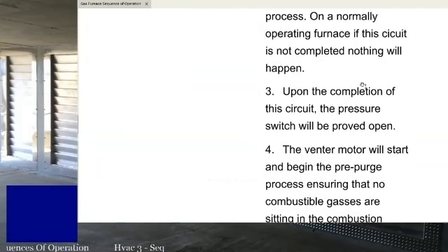Upon completion of this circuit, the pressure switch will be proved open. So on any furnace that has a pressure switch to prove that the induced draft motor is running, is everybody familiar with that? With pressure switches to prove induced draft fan motors?